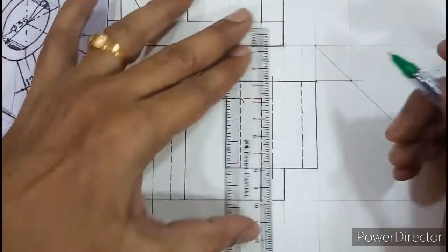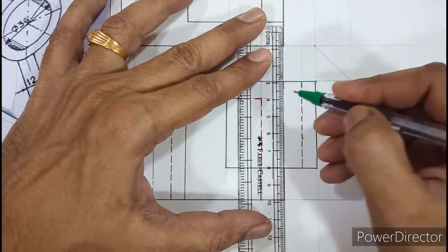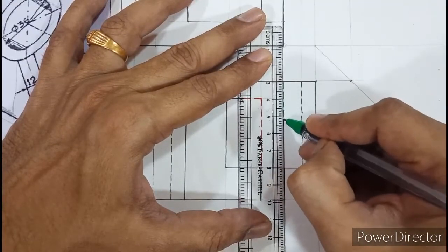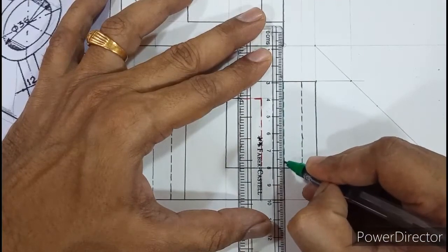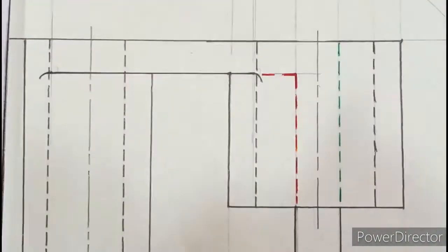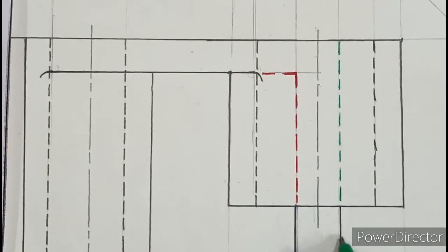You have to show by pencil only. So from here, if you draw hidden line, at the bottom you need to leave space. Again if I enlarge, yeah, this kind of space is required whenever object line and hidden line are in continuation. So this object line is in continuation with hidden line. So here you need to leave space.